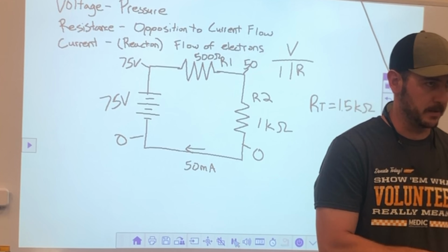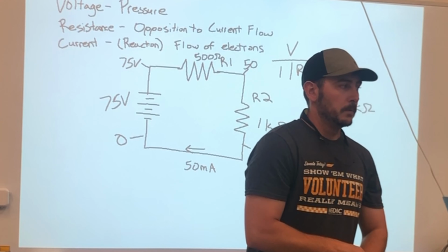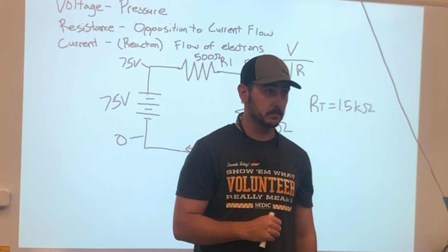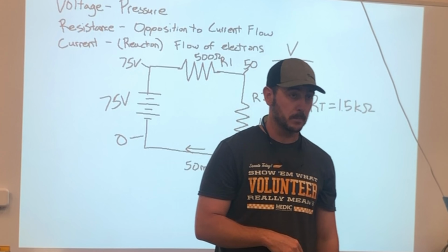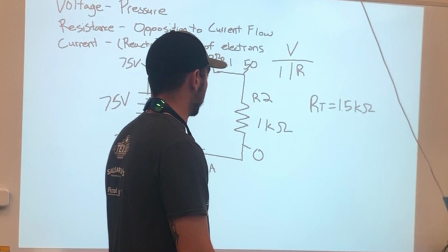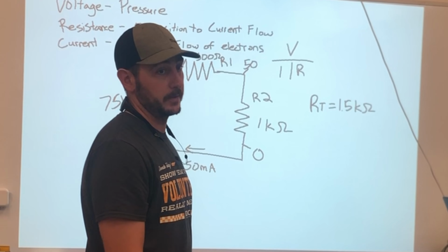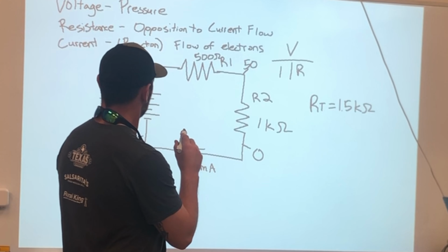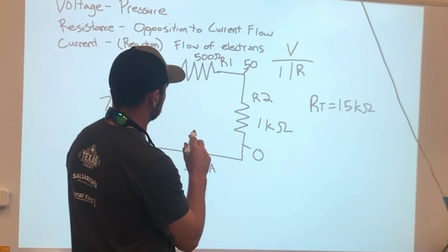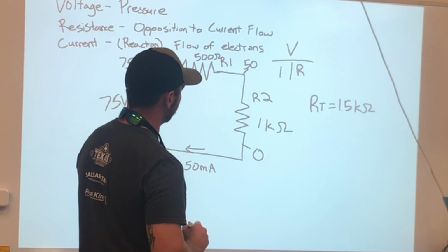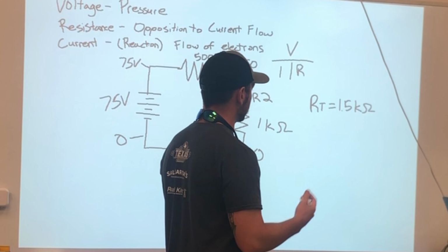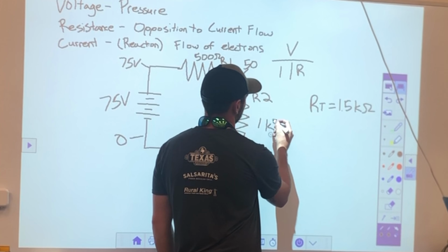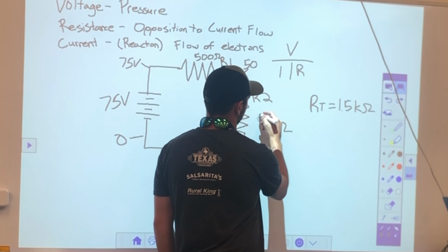Here's another rule for series circuits. Actually, this is for all circuits, parallel, combination, series. The applied voltage will always be dropped throughout the circuit. It's always going to drop across the circuit. We'll build this out here in just a few minutes. So, what happens if the entire voltage is going to be dropped, and I change this resistance right here to 1.5K?